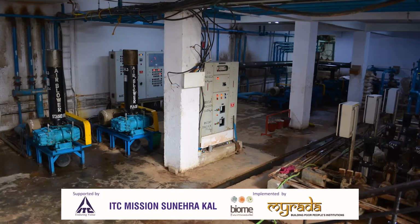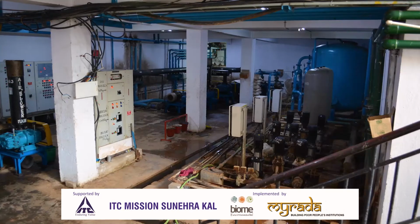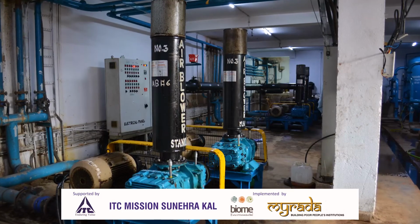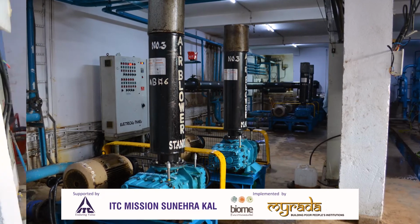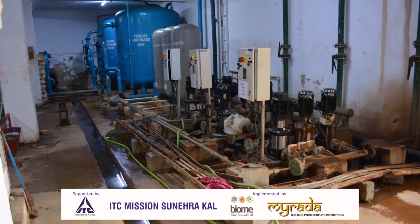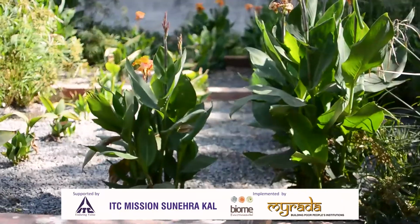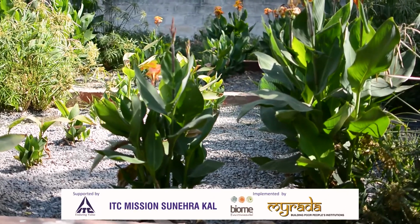Wastewater that is generated in an apartment can be very easily treated in an STP. STPs follow different kinds of technologies. The commonly used one is the activated sludge process, then there is a sequential batch reactor. There is a range of technologies. These are electromechanical STPs. You could also have low energy plant-based STPs which use similar technologies but which are slightly slower in process and give you treated wastewater as well. So once the choice is made between these two technologies.